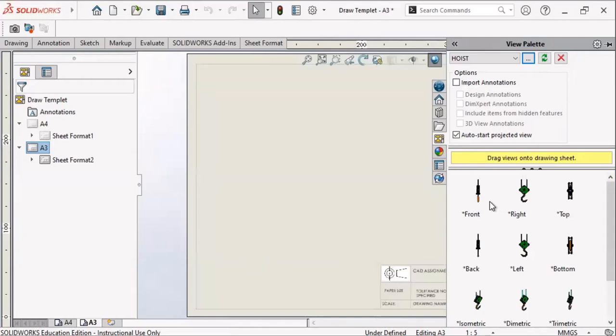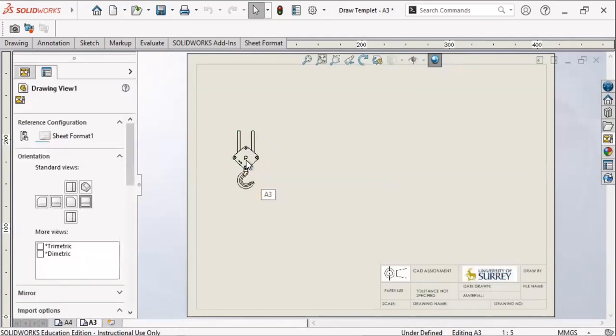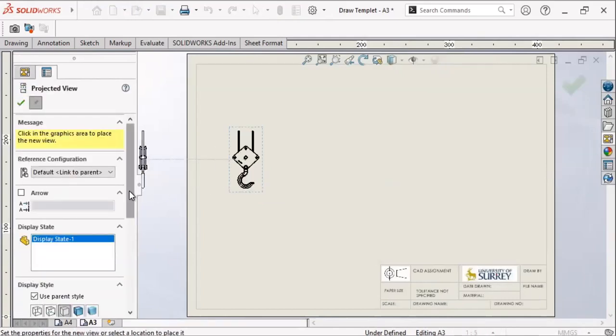Then you will see the front view, right view, top view, etc. If this is not the front view you want, if you want this one as the front view, you can bring this one in. You also can change the orientation of your model's front view. You do this in the same way as we explained for the component. So if you want this one as the front view, just click, hold the key and drag here. Right, okay.